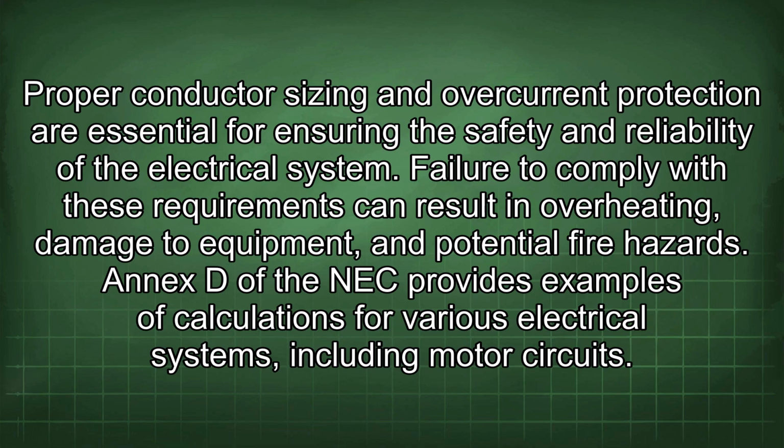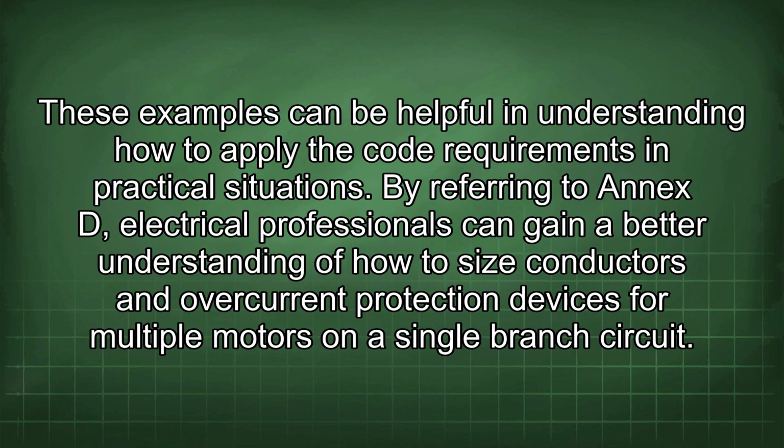Annex D of the NEC provides examples of calculations for various electrical systems, including motor circuits. These examples can be helpful in understanding how to apply the code requirements in practical situations. By referring to Annex D, electrical professionals can gain a better understanding of how to size conductors and overcurrent protection devices for multiple motors on a single branch circuit.